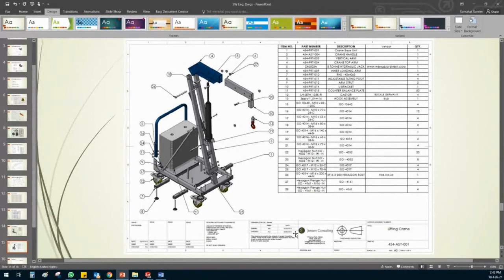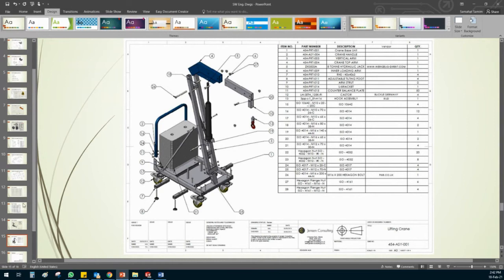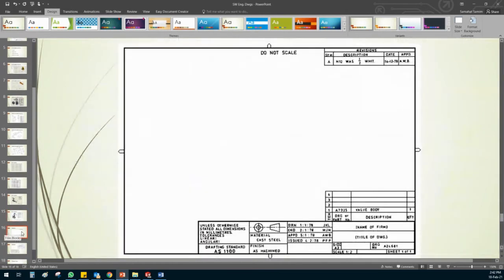And below you can see that the title block is filled with good information here. So this is a good example of an assembly drawing. One very important thing: don't forget, title blocks are really important. I want you to fill the title blocks with your name, your part number or name, the scale you use, the material you use here, and this is the sheet scale, and also how many parts you have.